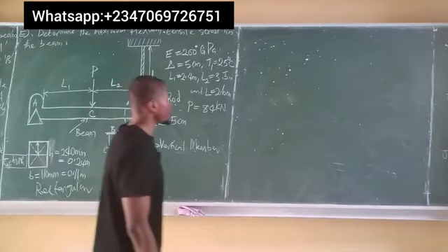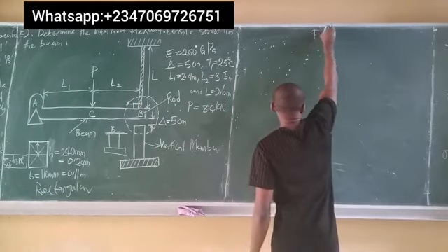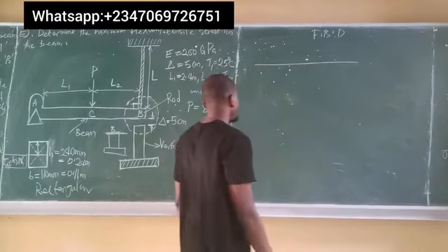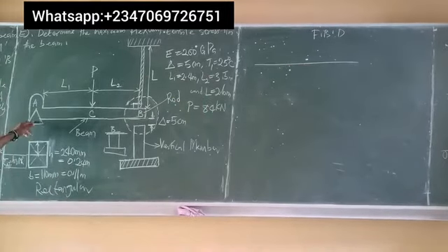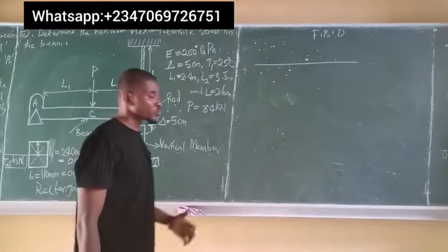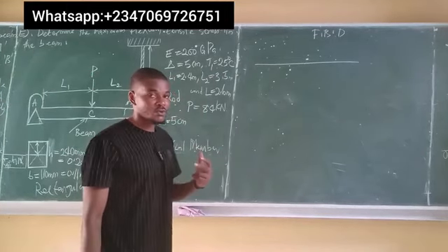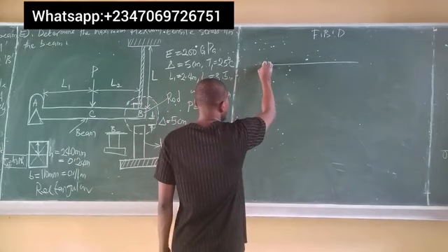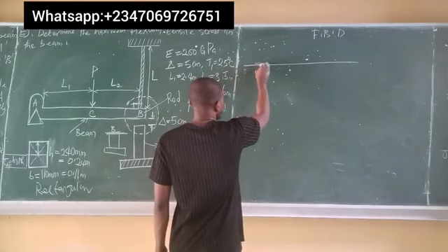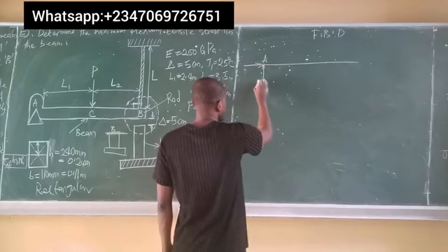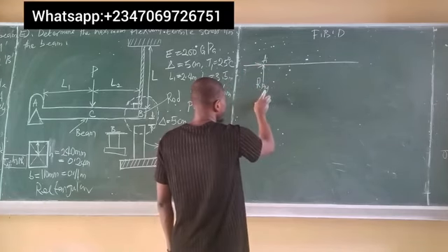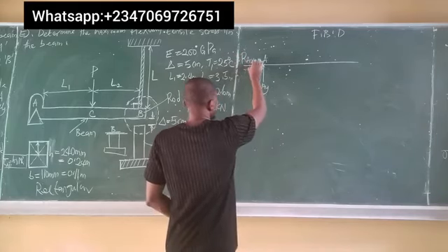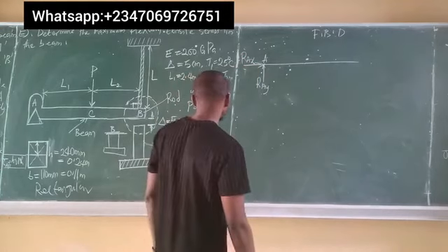All right, so we start first with the free body diagram. Free body diagram is simply a diagram of forces showing all the hidden forces on a system. Now at point A, we have a pin support. And for a pin support, we have two reactions, one vertical and one horizontal. So call this vertical reaction RAY, which means reaction at A, Y signifies vertical, whereas horizontal becomes RAX. X there signifies horizontal.